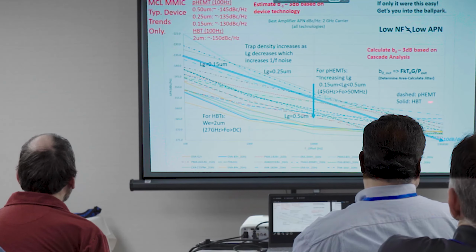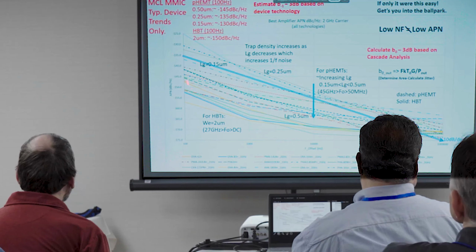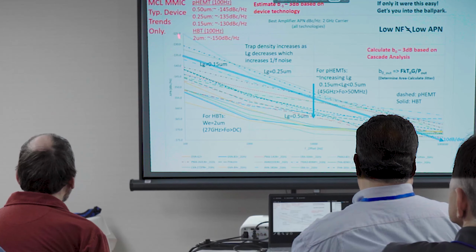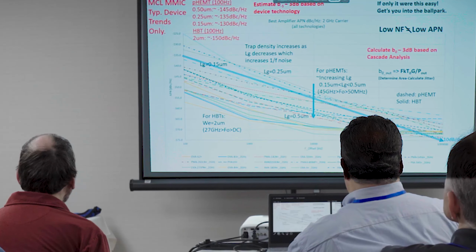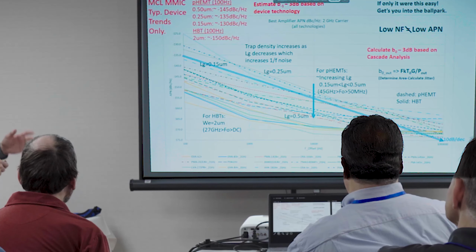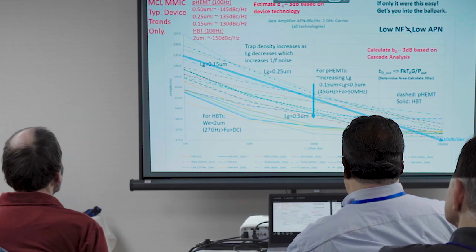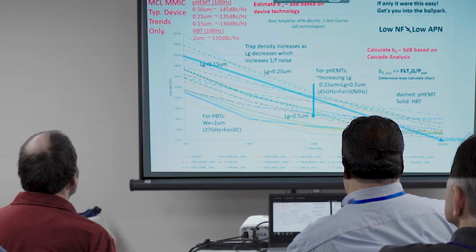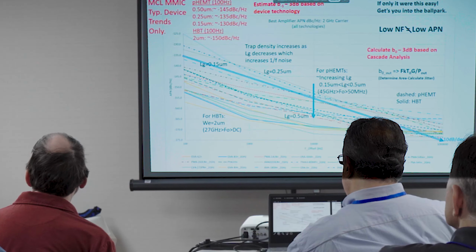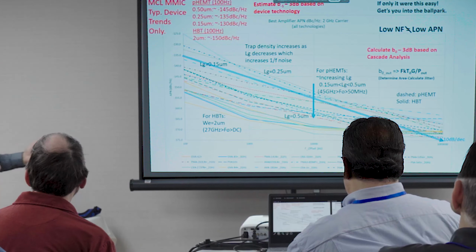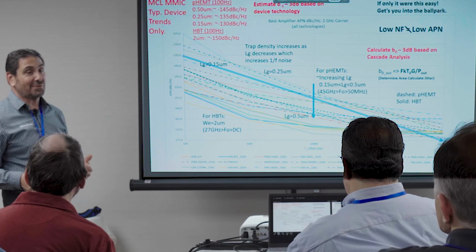But you'd better need the noise out there, because you're taking a real big hit in the 1/f region. So these are guidelines. You can approximate, add 3 dB if you want to be sure, to estimate the B minus 1 term. So you estimate that, you calculate the power spectral density in the white noise region, and you've just done phase noise analysis and cascaded phase noise theory.